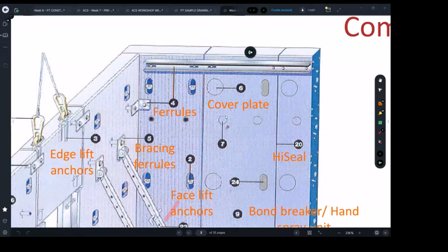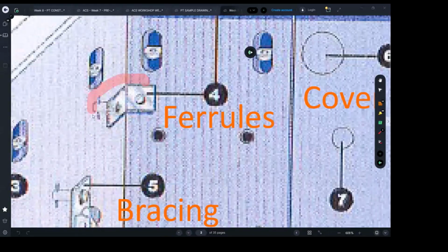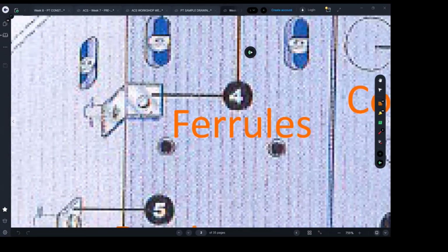purlins. Remember the purlins we talked about in the portal frame? Same thing here. We can install roof purlins, and those purlins are going to be supported on this tie, which can act as a beam to carry the roof as well. It's up to the engineering drawings what they want to do, and we will have real examples to talk about different cases as well. The ferrules here, to fix this equal angle bracket, there are ferrules back here, and those ferrules will allow for permanent connection. This is again a permanent connection.